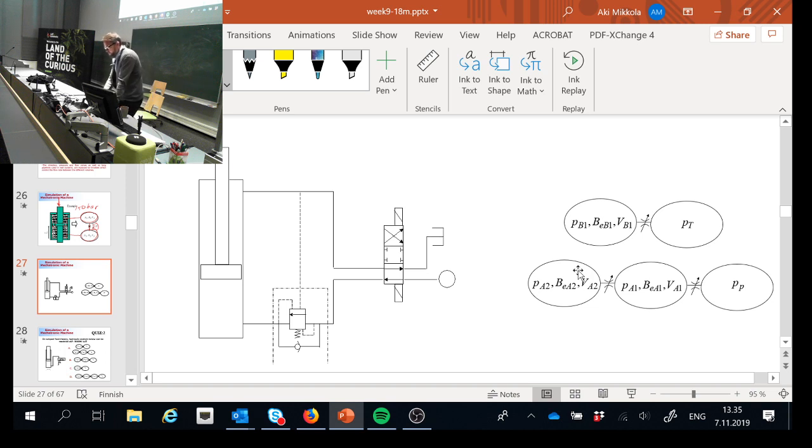So I have here a hydraulic circuit where I assume that there is a constant pressure source. Of course, in real life there is no such thing as a constant pressure source, because pressure is produced by a motor and a pump. But let's just say there is a pressure source where the pressure always remains constant, and that could be whatever value you want. Then I have here a direction valve that consists of 4 ports and 3 different operation conditions. It is magnetically operated like shown here, which is a typical scenario too.